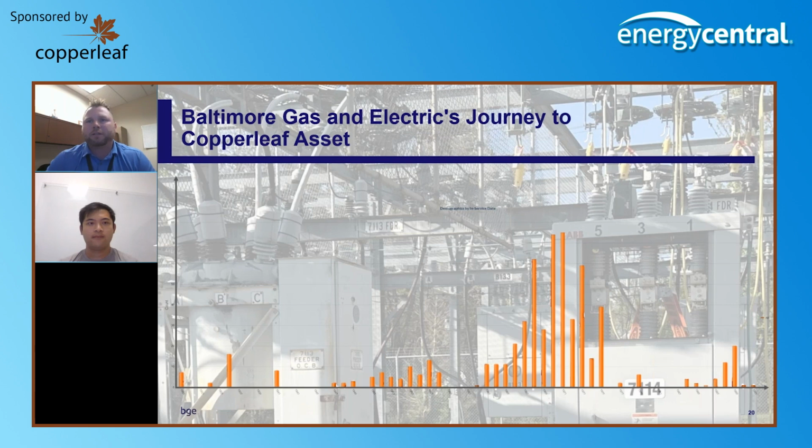So the challenge was, how do we go about identifying which of this population of circuit breakers we can replace each year, so that we are targeting the most impactful area with the goal of eventually getting rid of all of them. And so we started down a path of developing an asset health score to help us better understand this problem. So we worked with an internal analytics team here at Exelon to develop a model that took into account a number of different factors: CM history, age, oil sample data. We came up with all these health scores for all 600 some breakers.